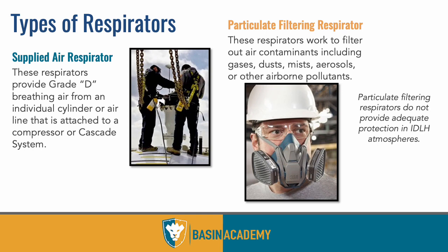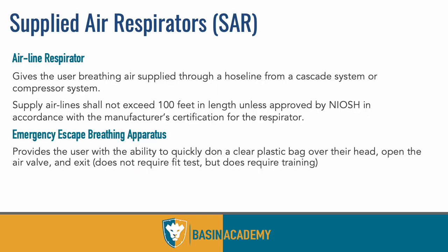We're very familiar with these now over the last few years, but this is the type of respirator that's going to filter it out for you. So supplied air respirators are the only type of respirators that are approved for H₂S over 2 parts per million. So basically at any level that matters to us at all. And so we need to have our own air supply that's being fed to us. There are different ways that exist for us to get that air.